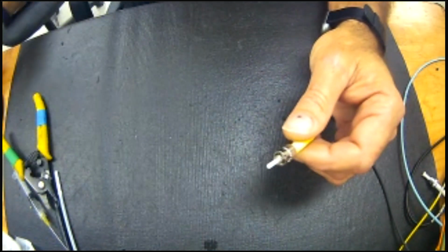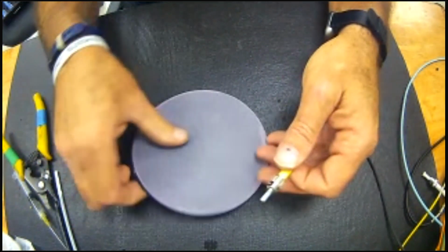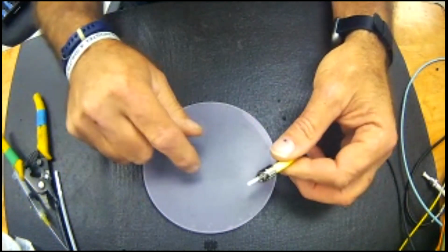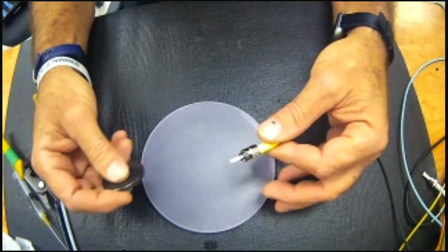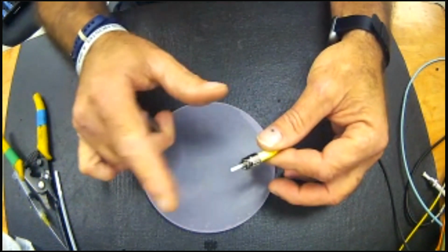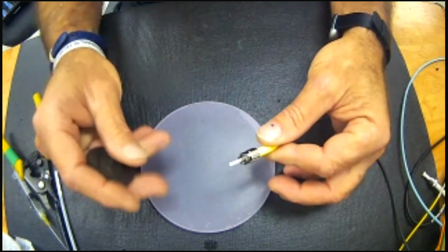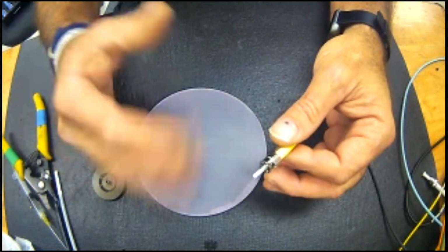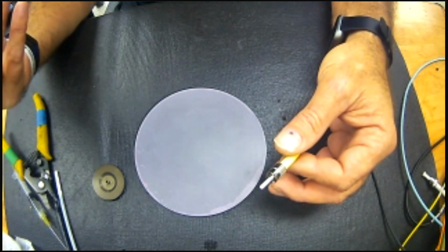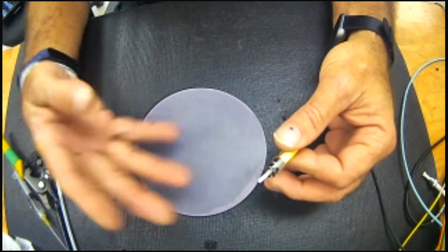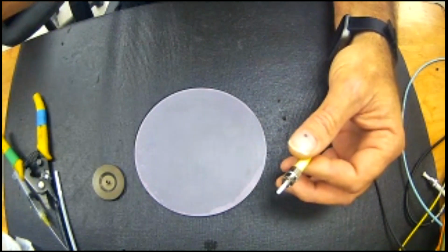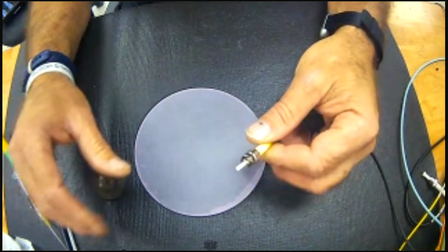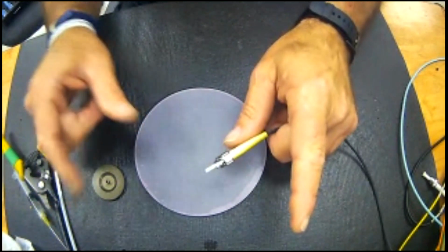Then I would switch to, this is another 90 durometer rubber pad. You can get them in squares, rounds, whatnot. I'm a big fan of 90 durometer. It does what I need it to do and doesn't pencil tip my contacts, tends to flat polish them properly. In this case, this is a diamond film. When I hand polish, I actually use the 4 stages of film. That's counting the 15 micron. This will yield you 25 to 30 dB of back reflection, which is very respectable for a field cable when it's point to point.